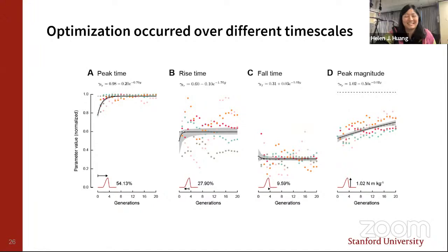So the torque magnitude is significantly lower. We saw that it was 0.68 Newton meters per kilogram. And the normal ankle torque magnitude is significantly higher, which was outside of the limit that we wanted to provide. We didn't want to provide anything over 1 Newton meter per kilogram. So it is the same shape. The parameters were chosen to define a similar shape, but the magnitude is lower.